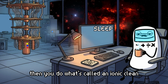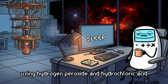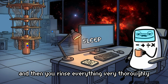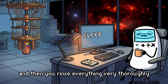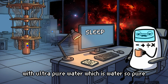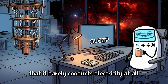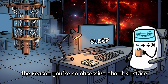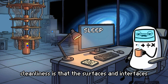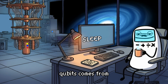Then you do what's called an ionic clean using hydrogen peroxide and hydrochloric acid, which removes any metallic contamination. And then you rinse everything very thoroughly with ultra pure water, which is water so pure that it barely conducts electricity at all. The reason you're so obsessive about surface cleanliness is that the surfaces and interfaces are where a lot of the loss in superconducting qubits comes from.